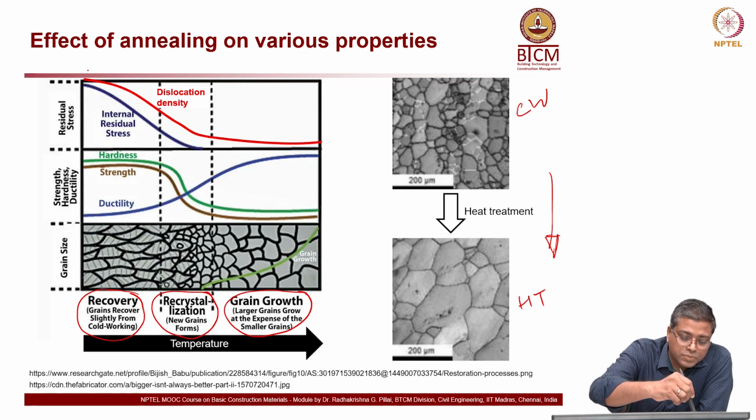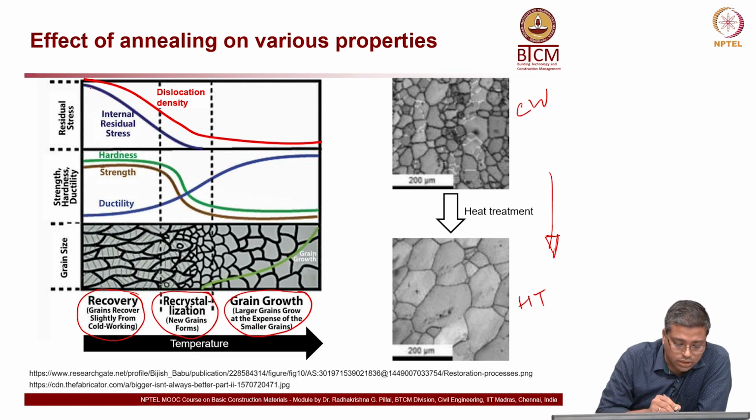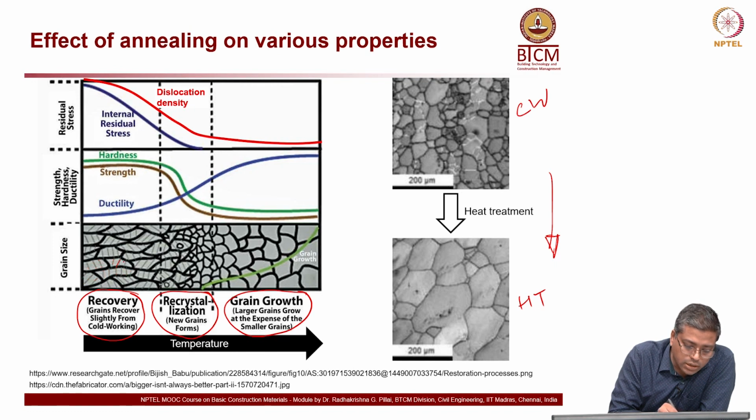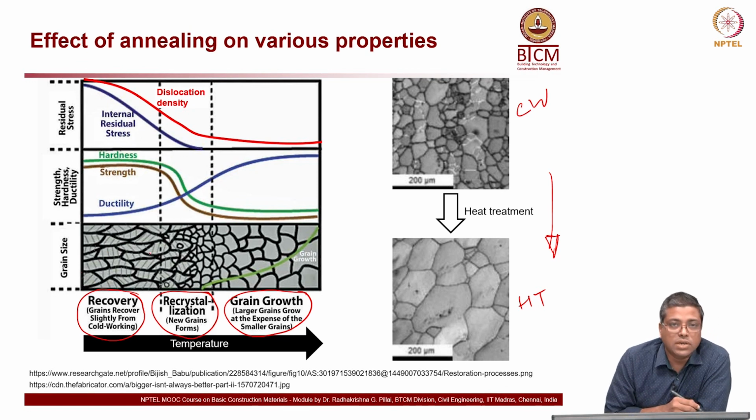Here, look at the dislocation density, the first thing to look at. You can see all these light gray lines, they are the dislocations present in the material. Then you have these dark lines, which indicate the grain boundaries. So you can see several grains over there.